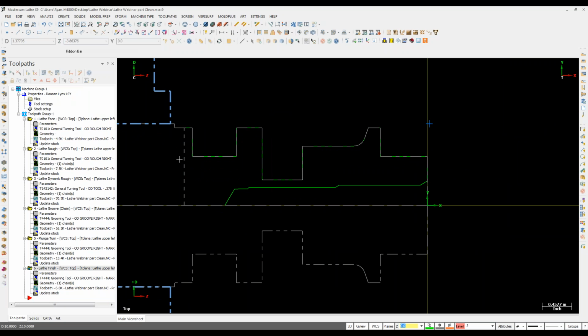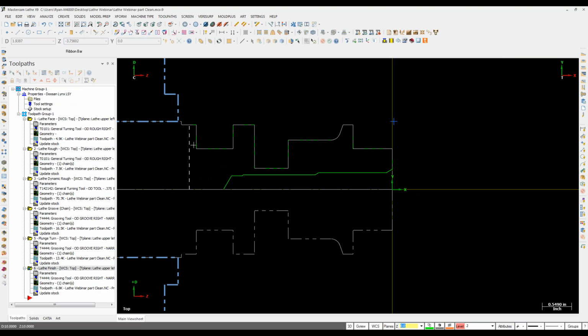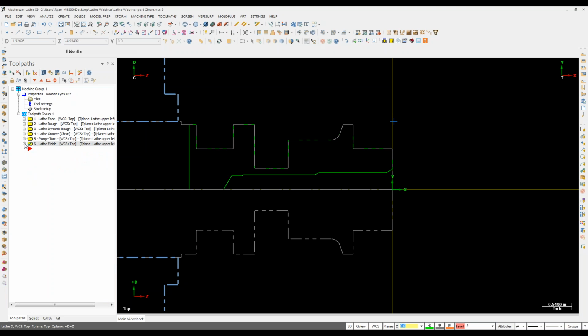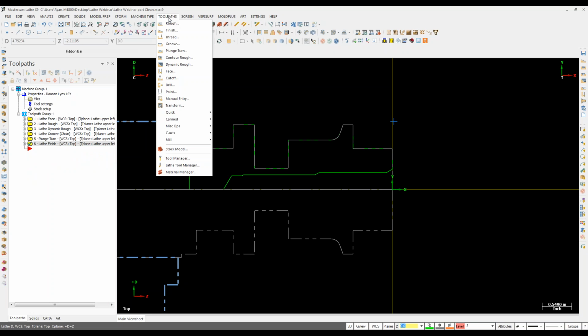Once that's good to go, I could just cut it off. Otherwise, if I had some back work here, or maybe I want to take a face cut, I'm going to transfer it to a spindle if my machine has that. Now, this is going to be using what we call POCO for short. It's basically a pickoff, pull, and cutoff. What that's going to be doing is it does require some specific post work to be done to create some logic and make everything fine-tuned correctly. So that's going to be stashed under my toolpath, miscellaneous op, pick off, pull, cut off.